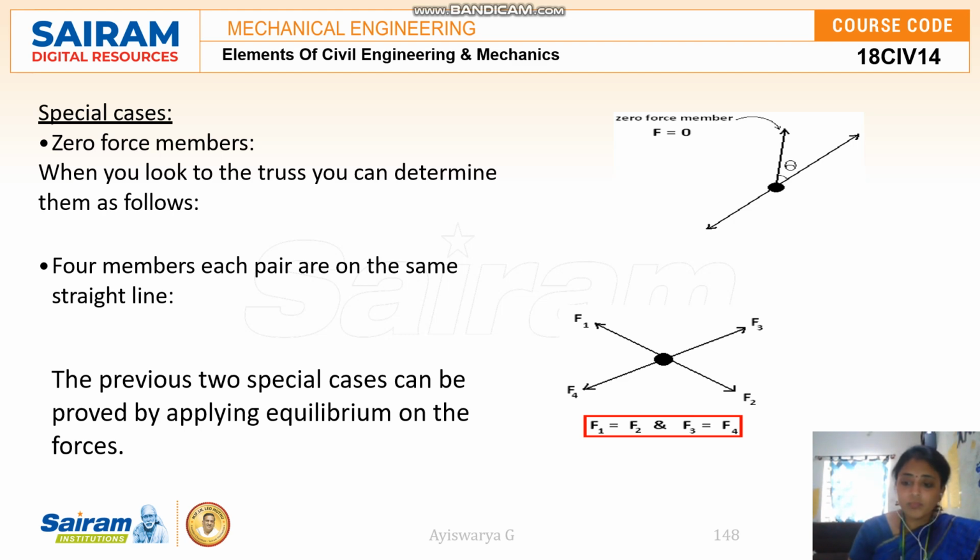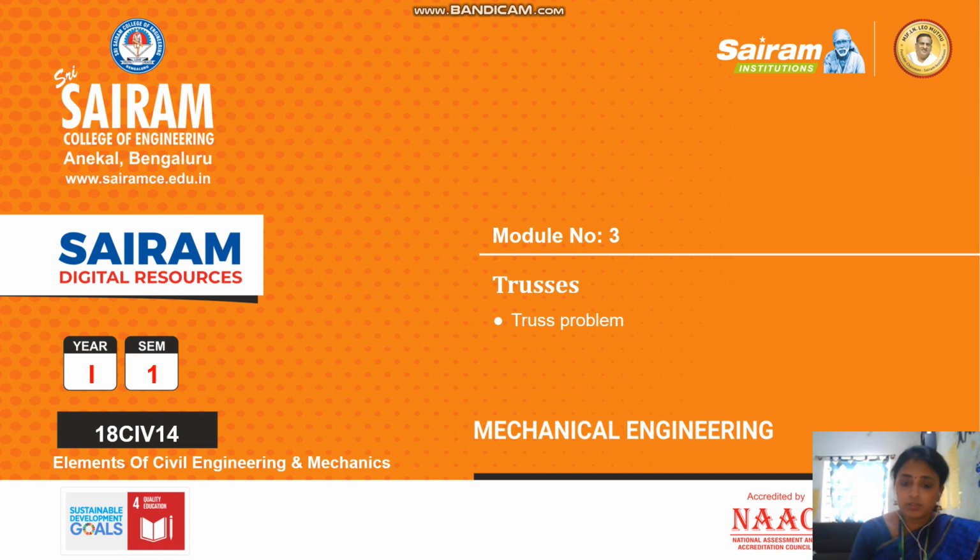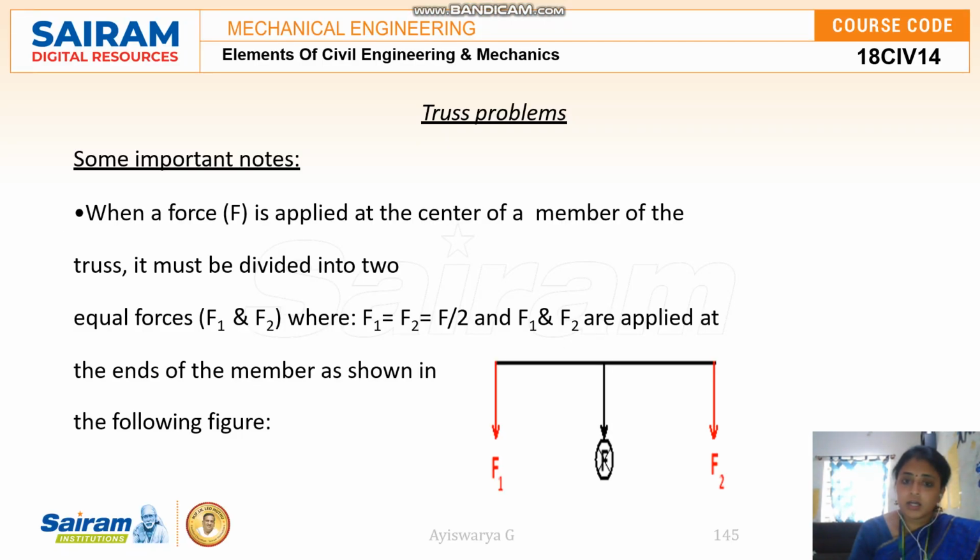Okay guys, so I conclude the introductory part of the truss with this. We shall see how to solve those truss numericals in the next lecture video, and try to understand the difference between method of section and method of joints. It's easier to find the forces by the node by node method of joints, using the equilibrium condition. You can easily solve the unknown forces.